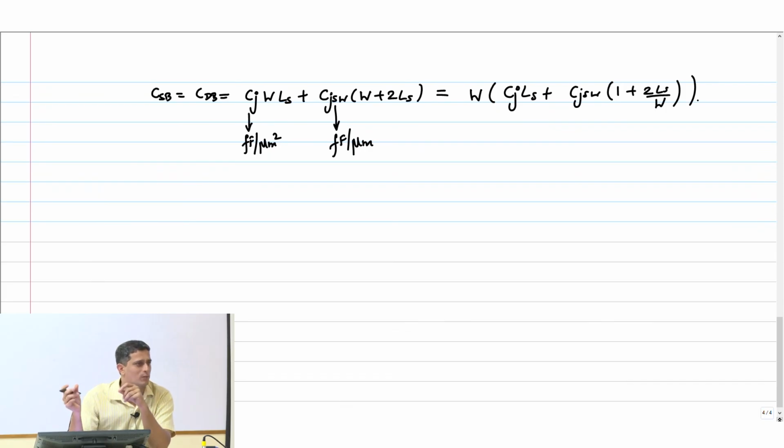It's Y equal to mx plus C. That's the C of the equation. W is basically the slope of the equation that we are talking about. Okay, so as a designer, this is what you need to know. If I scale W, all the capacitances will scale linearly to a first order, right?